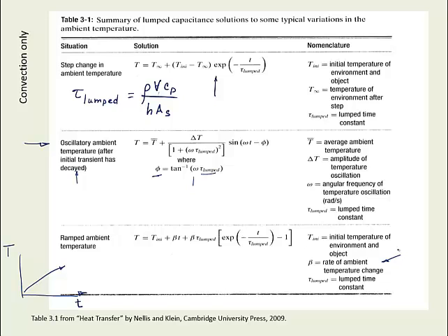But due to the fact that we have capacitance of the temperature sensor, it does not quite follow the temperature change of the line, and this equation can be used to calculate at a given time instant what the response of a temperature sensor would be to that changing free stream temperature.